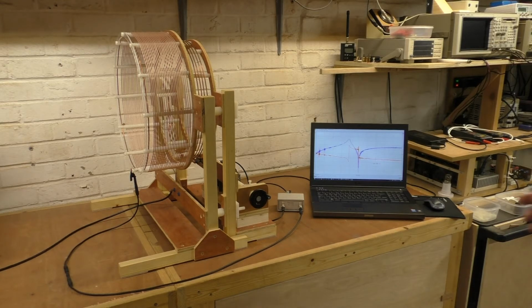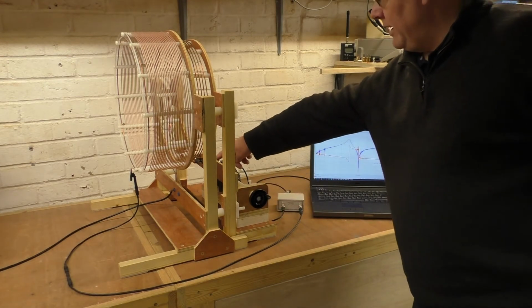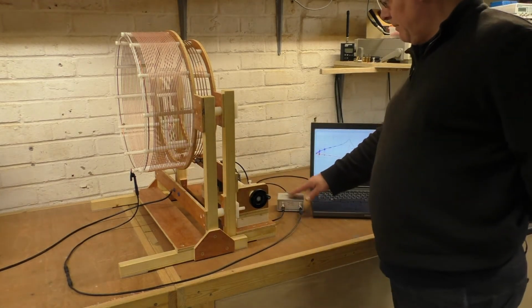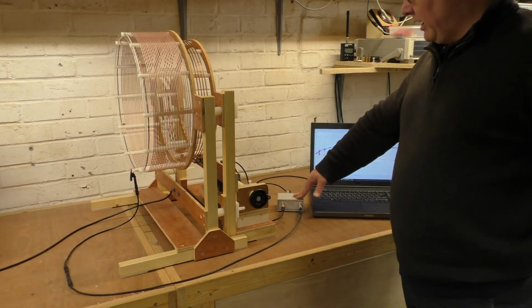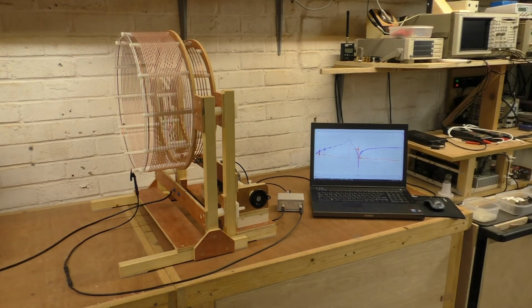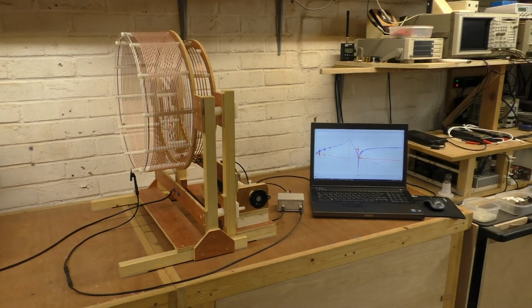We are passing a certain amount of power, nominally 0 dBm, in here, and we are looking to see how much power we get transmitted back to the vector network analyzer, and also what's reflected back down the input as well. So S21 and S11, and if you reverse those, you could also be looking at S22 and S12. That would be the characteristics of full 2-port power characteristics, which is typically what you would use a vector network analyzer for.